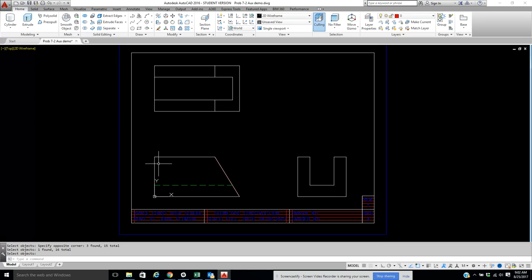Okay, so now you see the drawing a little bit better. Now notice, this area here is true shape. This little area here is true shape. This is not true shape. This is foreshortened because it's on the slant. The side view, it looks like it'd be true shape, but look, it's slanted, so this really is not the true shape. So, a couple of things on how to do the 2D drawing, so you need to understand that.